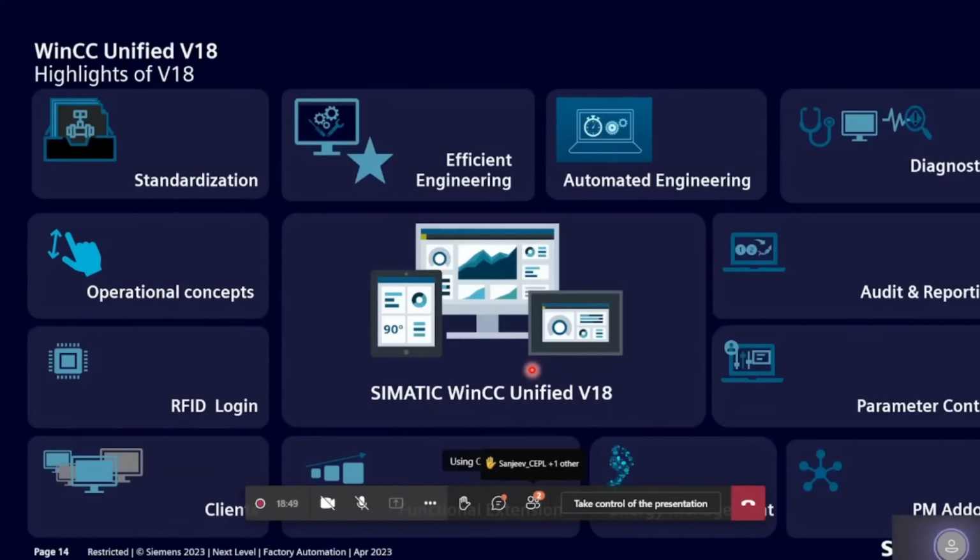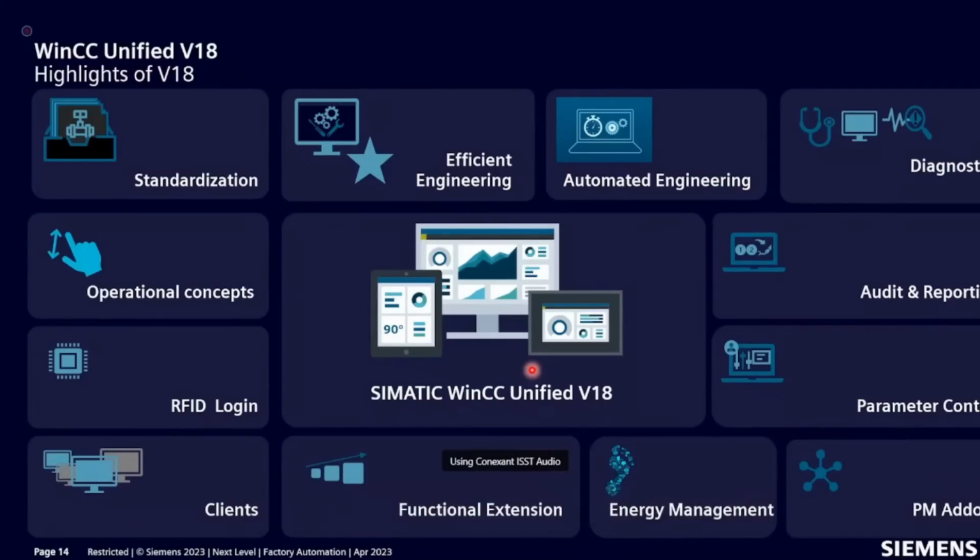Omkar: I want to ask Dhananjay, can we use this web server parallel with the unified panel, or can only one device be operated at the same time? Which web server, PLC web server or unified panel web page? Unified panel web page. It can be parallel. In Comfort panel we have functionality called smart client, where the same screen will be available on the client station also. But in web client, it will be a parallel operation.